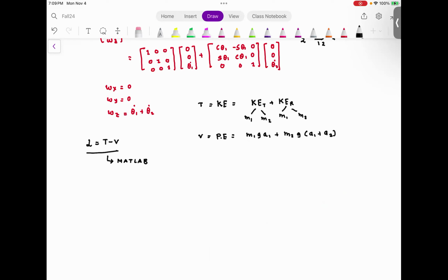Now, you would appreciate that for a simple 2 degree of freedom robot, this problem becomes quite complex. And in here, your first revolute joint and the second revolute joint were parallel to each other, which means you did not have angular velocity components in X or Y. When you have a robot which is R perpendicular R, maybe parallel R, a manipulator configuration or a spherical wrist configuration, you have to follow the same approach.